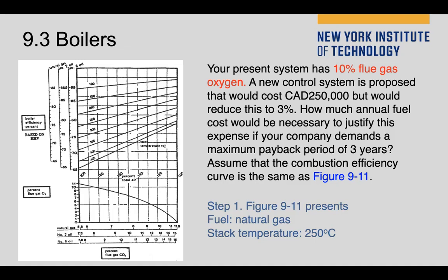So a higher percentage of oxygen in the emission gas is not good, because the combustion is not consumed very well, since some extra oxygen will remain. If we have a lower percentage of oxygen, it will show a better performance of the system.